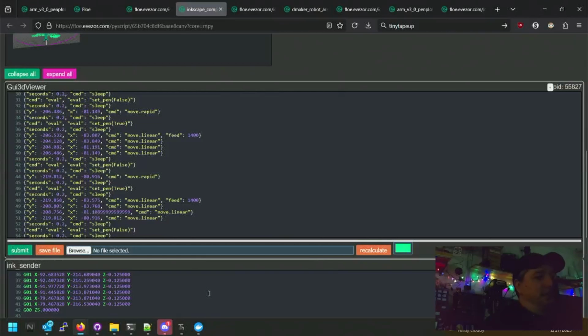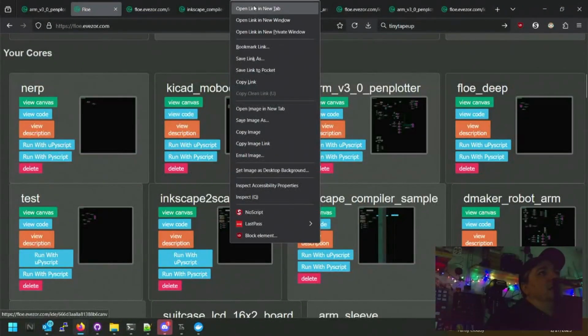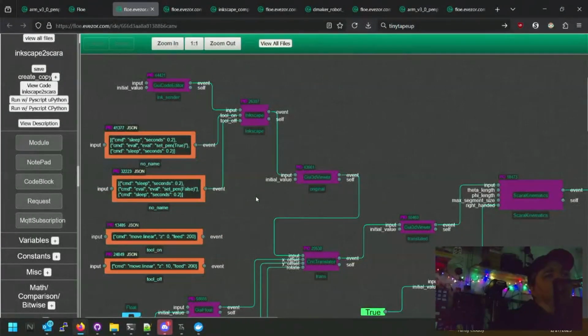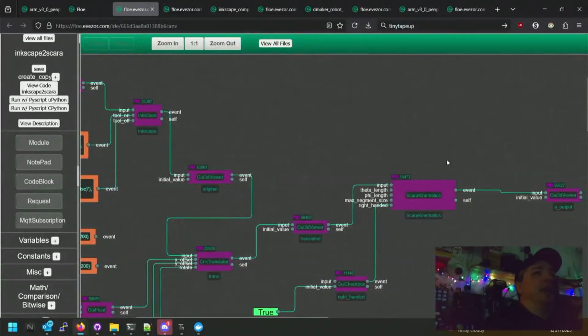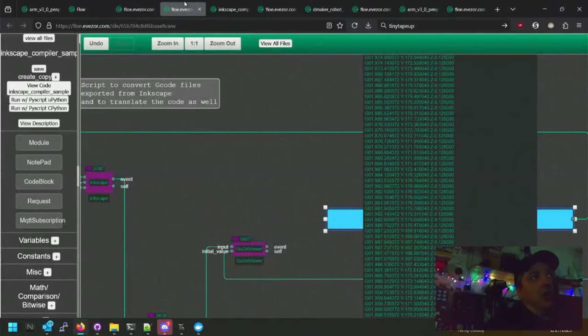Does not. Let's go ahead, and I'm going to copy all this. Let's open it in one of the ones that does some SCARA transforms. So again, the same kinematics processor that we have for the robot, we just dropped in here, and we can pre-compile some code if we want to. So you can either drop G-code in and feed it back through and have the robot run straight G-code, or you can pre-process some of this and also send in these JSON lines as some pre-compiled code.